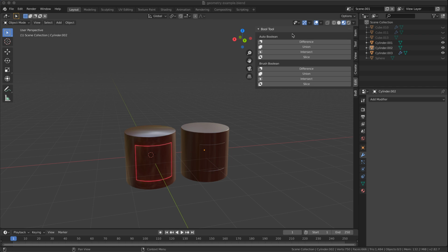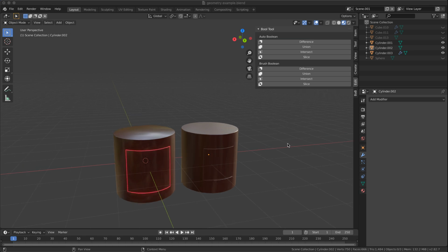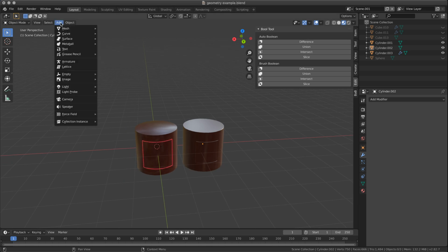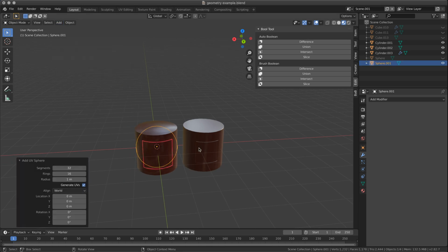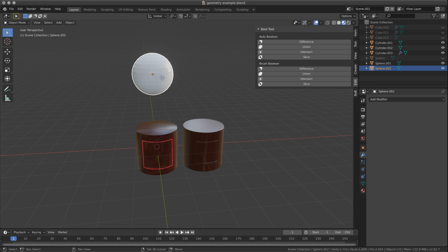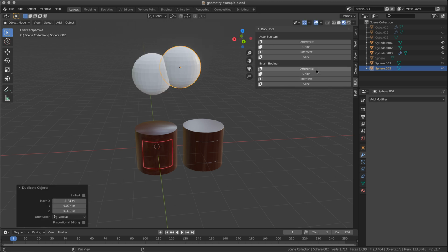So BoolTool, it's a very interesting add-on. It's included in Blender. It's already in the bundle. You just need to activate it, and it will let you create Boolean on the fly. You create the first object, create the second object, and then you decide what you want to do, difference, and it doesn't work because you have to select the...